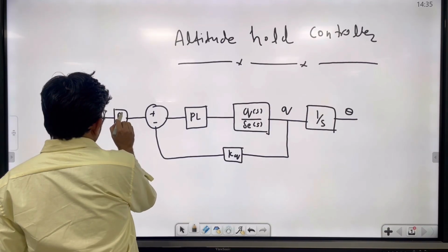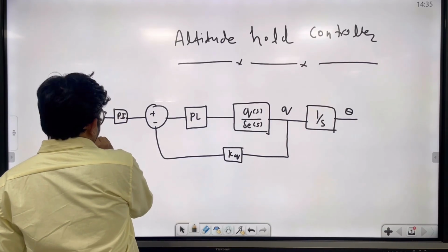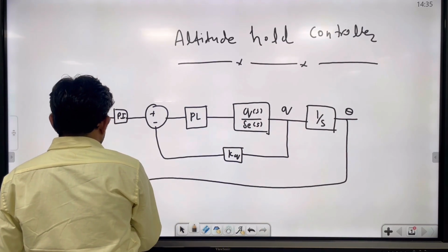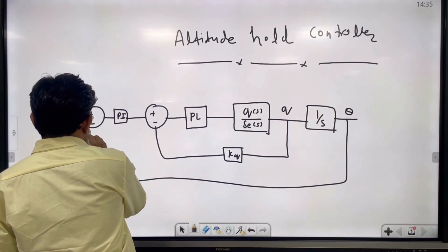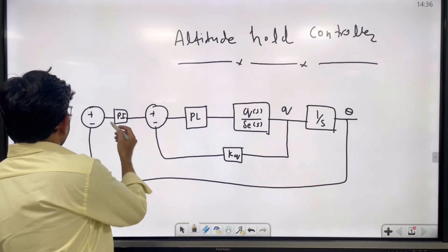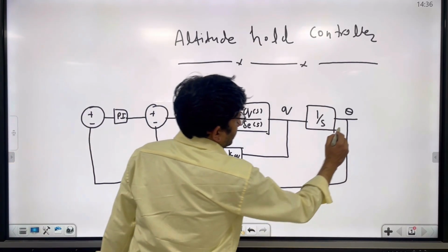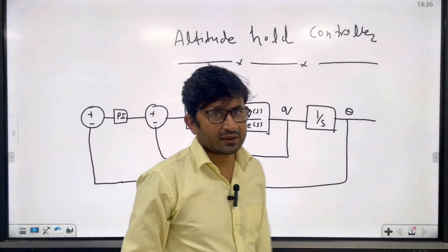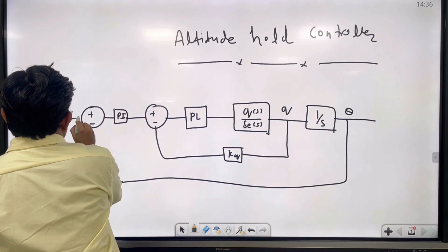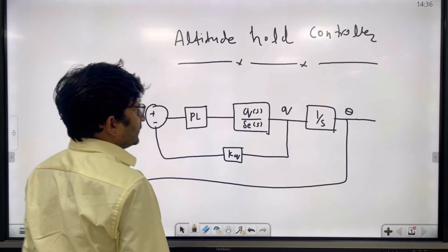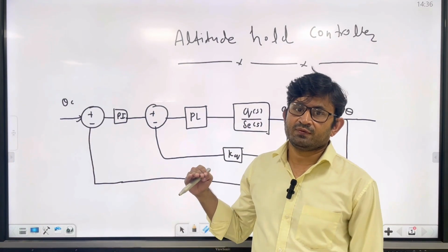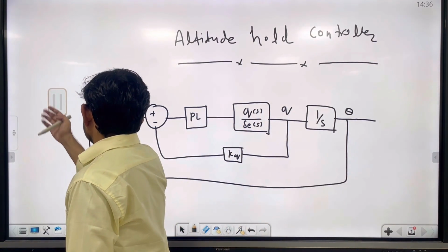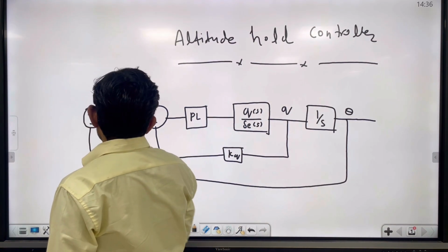So after that, here you will have a PI controller, and here you will get the feedback of theta, right? Up to this we are clear. Here you can command some theta value, theta command value. Okay, now from this we will add one more loop. Okay, so instead of directly commanding the theta, we will generate theta command by this.